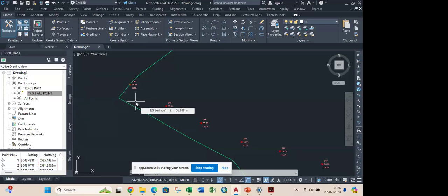It doesn't mean you have to follow the center line the surveyor established on site. So you, the designer now, you're not designing based on wanting a straight tangent and a curve, but based on your passing sight distance, stopping sight distance, and all. We'll be taking that into consideration, that if I'm driving now, I'm able to see a longer distance, at least 600 meters or minimum 400 meters, before I overtake a vehicle coming. So those are the things you'll be taking into consideration when you are doing the total alignment of the road.